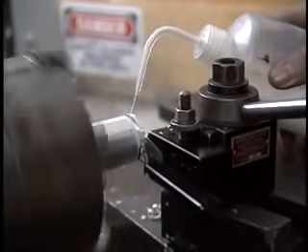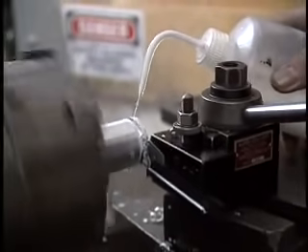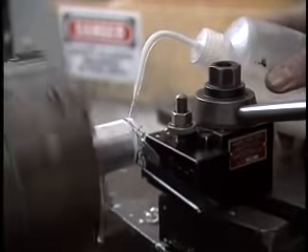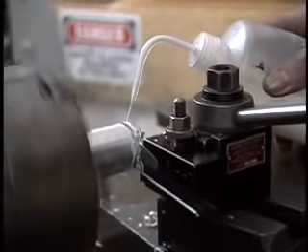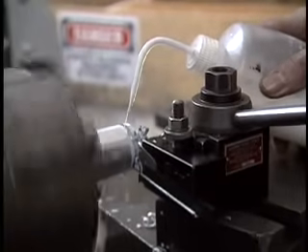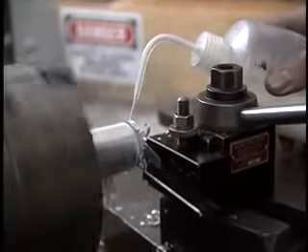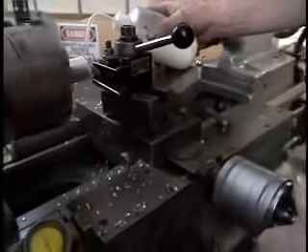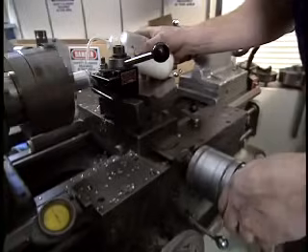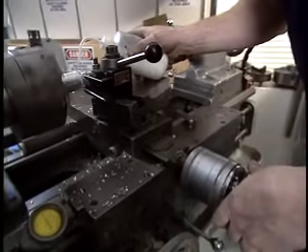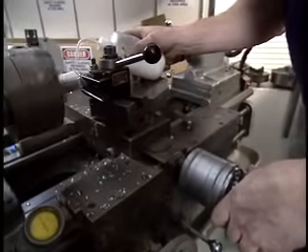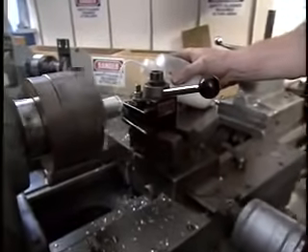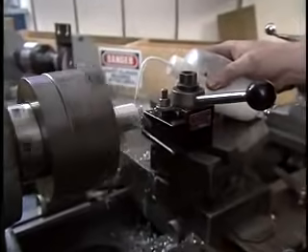What's going on there is that I've stopped turning the crank, changed the position of my hand on the crank, and during that time, very little cutting goes on and it chatters a little bit. I'm feeding this by hand so that if something unexpected happens, such as the tool binding up, I can very quickly withdraw the tool from the part. Now you can hear the pitch, the chatter go up slightly. That's usually there. You can use that as an indicator. It's just about the time when you'll have completed the cut.